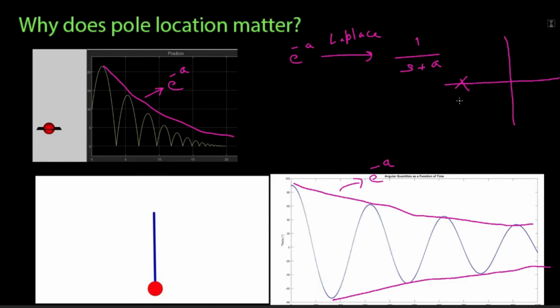Therefore, we can see that for poles on the left hand side of the imaginary axis, even if the response is unusually high for poles, this high amplitude will decrease with time. Therefore, such poles can be considered stable poles, and such systems can be considered inherently stable. These systems have the capability to withstand a sudden force and come back to their stable positions.